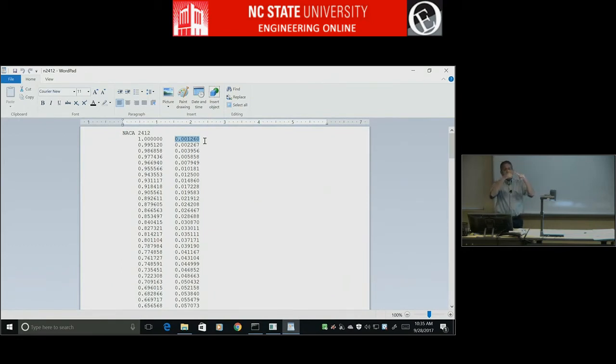You just start from the top trailing edge, go around to the bottom trailing edge, and leave it as an open gap, and Xfoil understands that. If you try to close it, it's not meant to be closed, is what I'm saying. Internally, Xfoil will take care of that. Any questions?